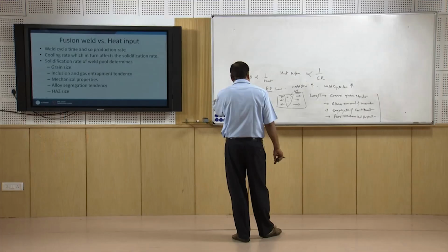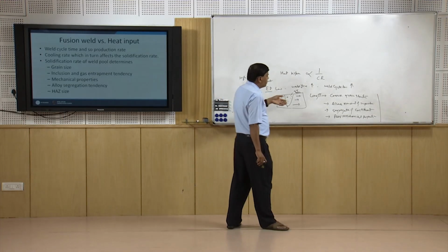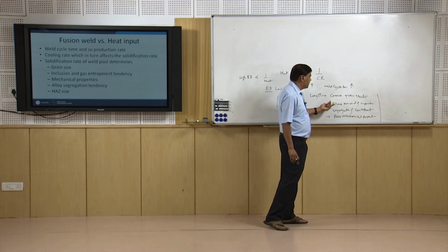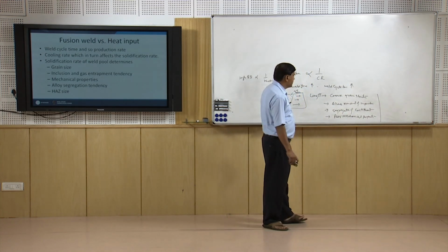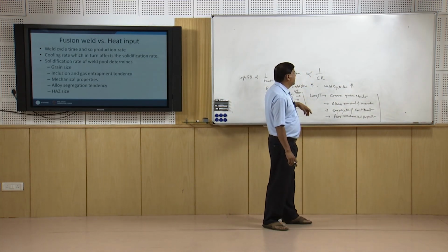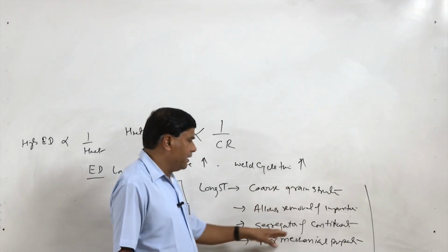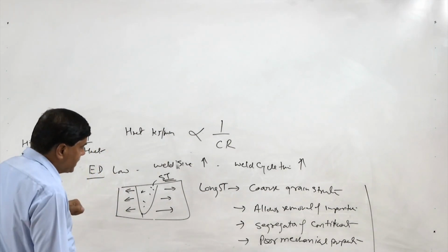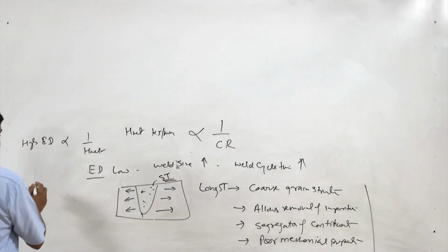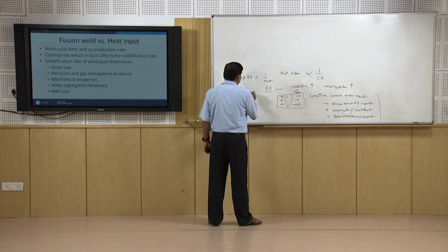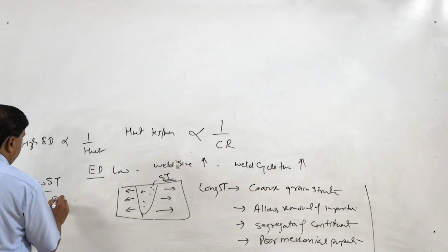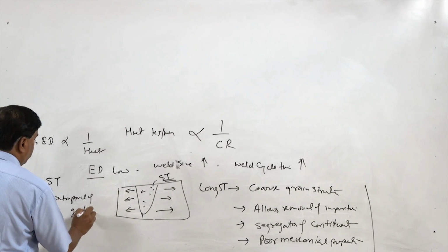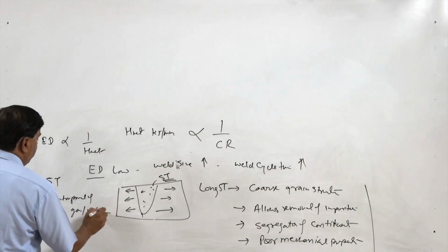So it is not always good to have the longer solidification time. It is not always bad either, because longer solidification time helps to remove the impurities in the form of inclusions and gases, but it is adversely affecting in the form of coarse grain structure and increased segregation tendency. On the other hand, if the solidification time is very low, that is also not very good, because entrapment of the gases and inclusions will be promoted.